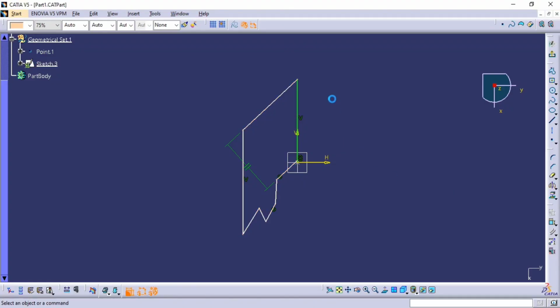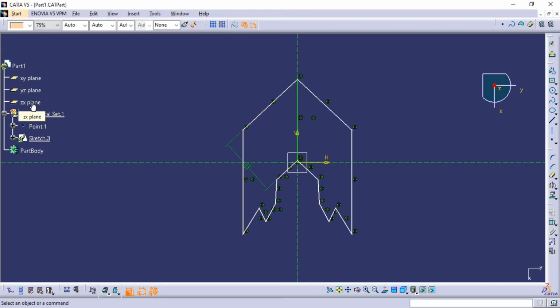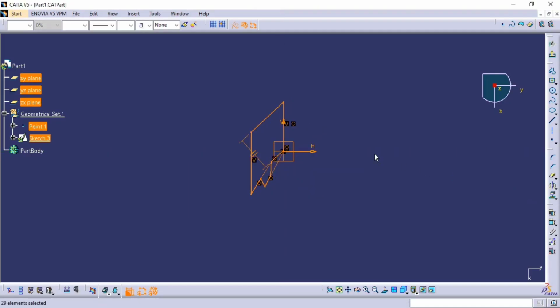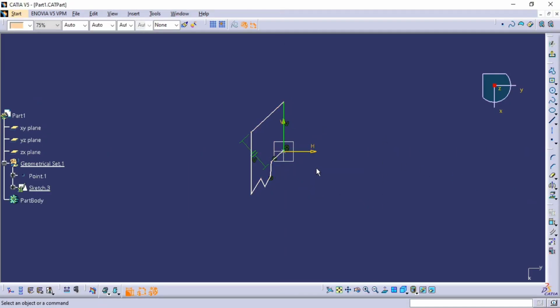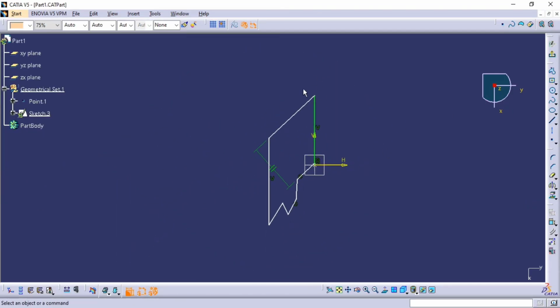Okay, in order to use this feature, you have to select all the features earlier and choose a mirror feature and choose a mirroring line. Okay, I have chosen a plane. So this is how that mirror tool will work, and the symmetry is nothing but, if you use a mirror, whatever the things that you have selected will be projected to this side also.